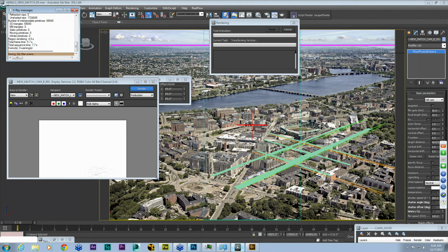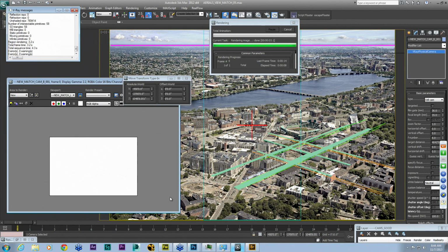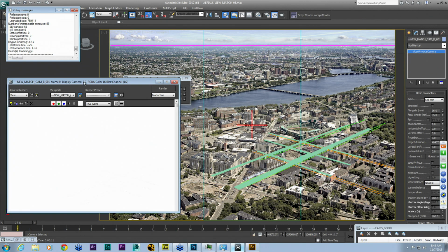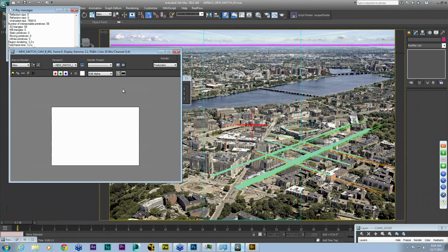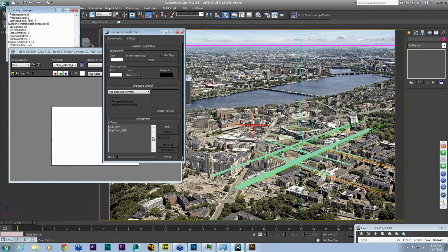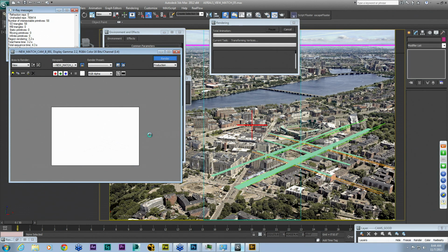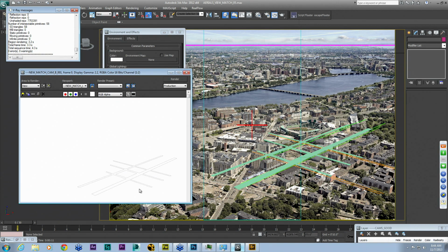And what I've done, when I do camera matching, is I'll make a V-Ray override material or a self-illuminated override material, and I use the V-Ray toon shader to give my sight lines that sort of nice line on the edge of the geometry, right?